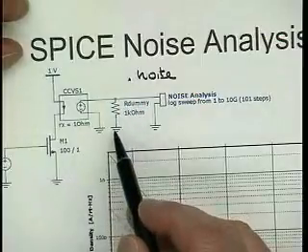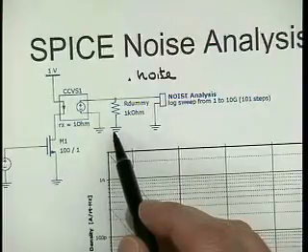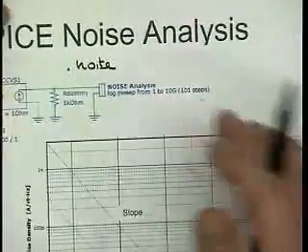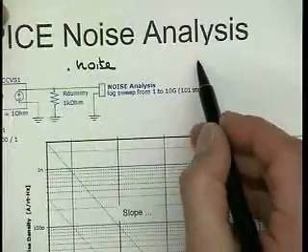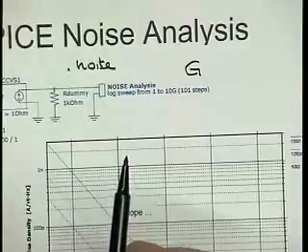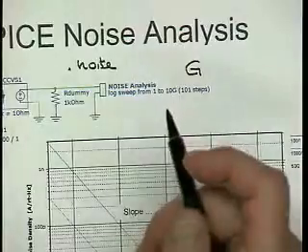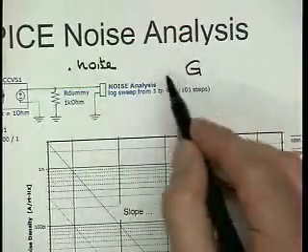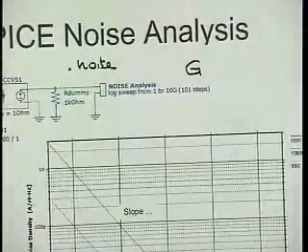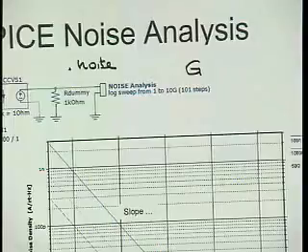Sometimes you do have a need in SPICE, hopefully only sometimes, for a noiseless resistor, and there is a trick to make those. SPICE has a GM element, G, and of course you can set it in feedback on itself, basically a diode-connected transconductor. Interestingly enough, those synthesized resistors made out of transconductors in SPICE don't exhibit noise, whereas real resistors usually do, and in some more advanced versions of SPICE there is a way to turn the noise off.